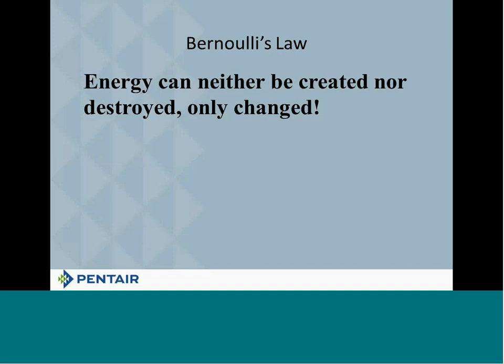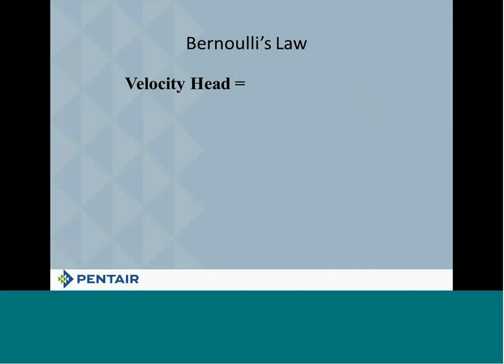All right? Now, it's very important to remember that energy can neither be created nor destroyed. It can only be changed. So we're taking energy from one form and converting it to another form. All right? Now, again, remember I said head in our industry means the energy. So we're going to look at the formula for velocity head or velocity energy. And the formula, don't panic on this one, you don't have to memorize. Here's what it is, though. V squared divided by 2G.